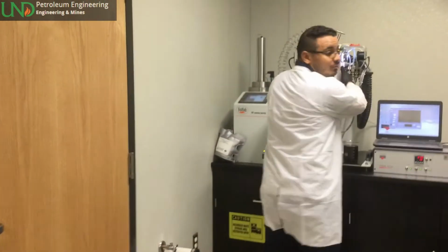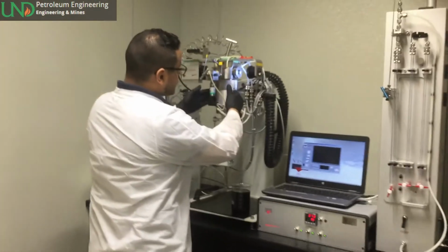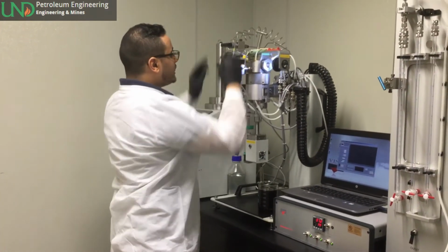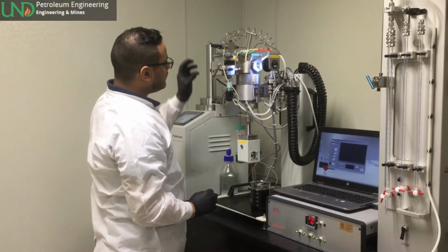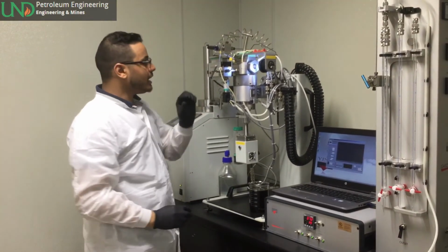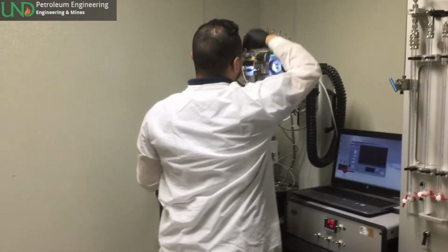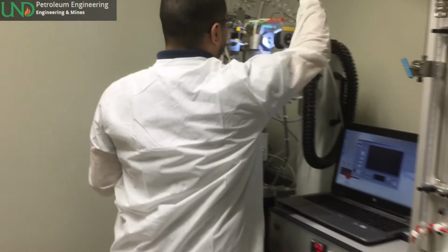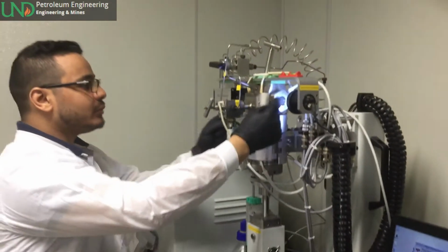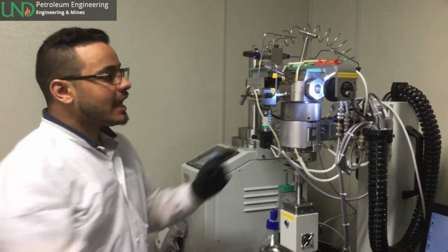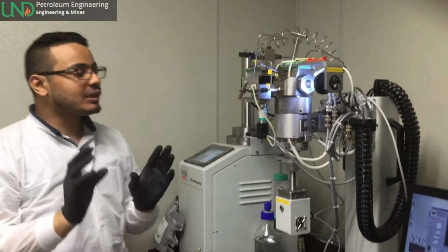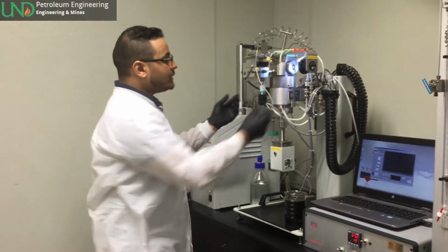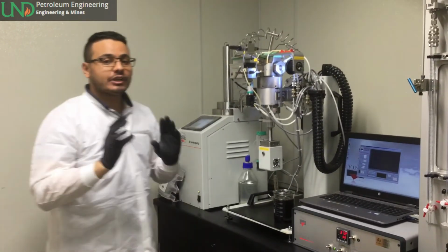And here is the main component of our system, which is the head and PVT cell. The head is composed of valves. With this micro valve we can control the specific volume of the sample, and through these lines we can transfer our fluid samples from the oil reservoir or gas reservoir inside the PVT cell. And here we have 2 glass windows, through which we can visualize the interaction between oil and gas during the flash test. And we have light and a camera to record this interaction.